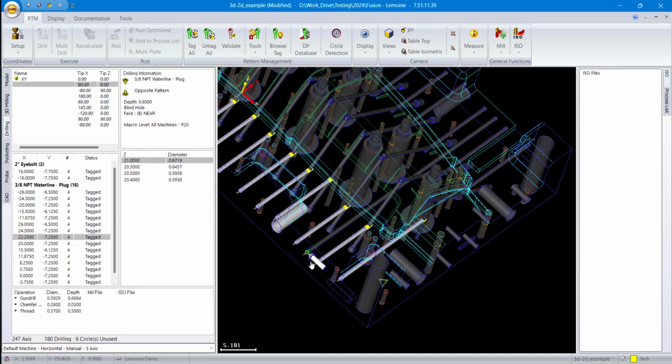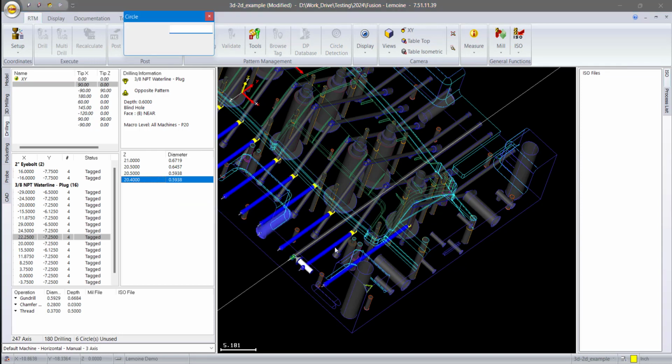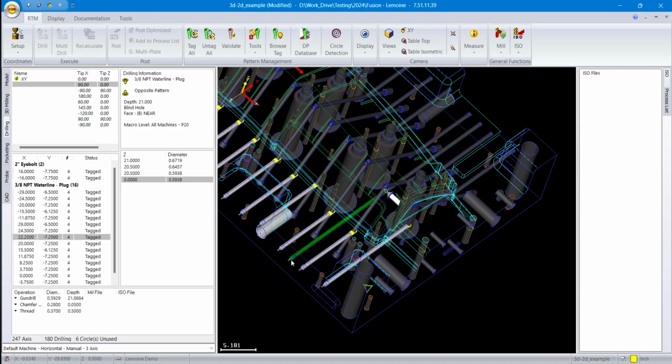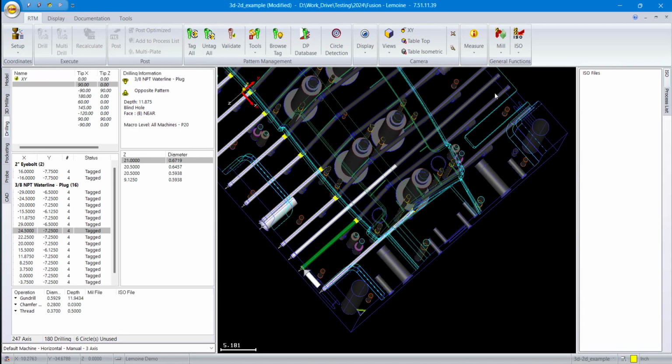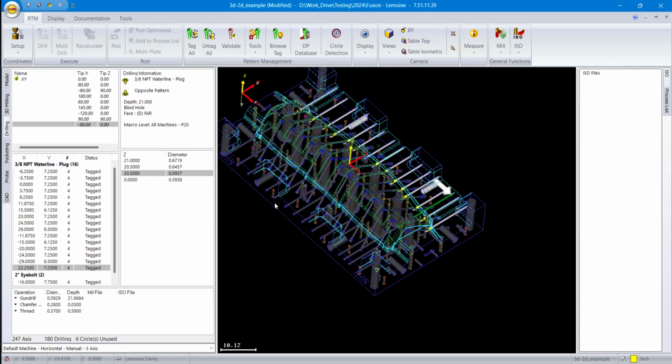So what I'd like to do is split it in half so it's a little bit easier to drill. From this end, I'm just going to move this one, and I just drag it by hand if I like, put it somewhere near the middle. I have a little incremental absolute switch here, and what I'd like to do is just put it at the center of the mold. So I say OK to that. And you'll see now this water line is split, and it goes half from one side and half from the other side to make sure that we're getting what we want.